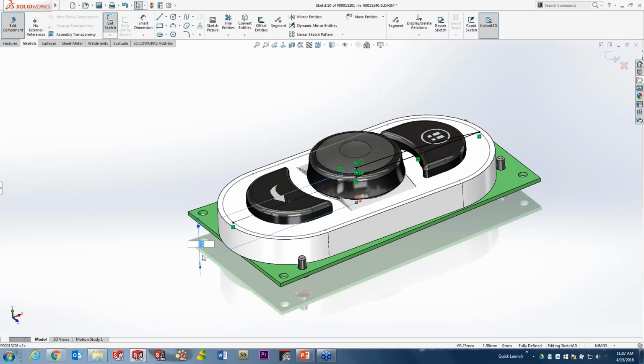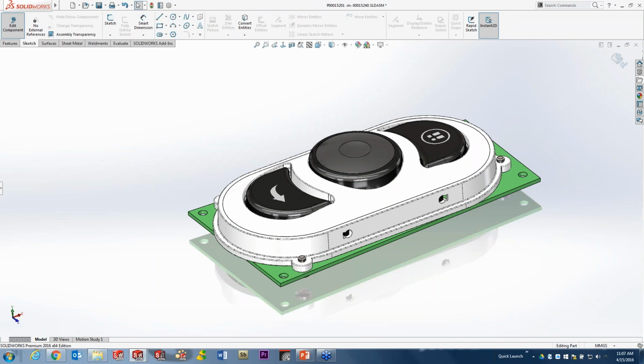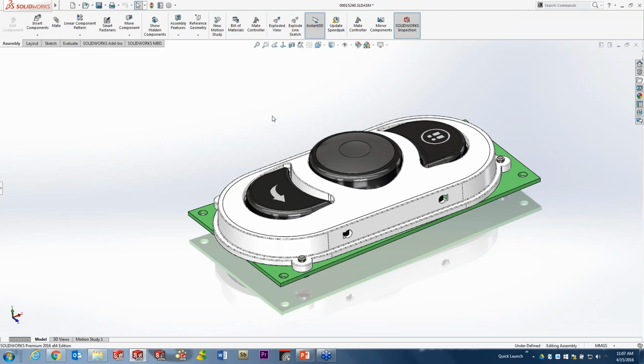Now by making a change to this feature here, we'll just bump that up to 20. Now I have to exit my sketch, which in the upper right-hand corner, we have our confirmation corner. Well, the D key will also bring that directly to cursor position. Now you can again set that to anything you'd like, including a button on the side of your 3D mouse if you'd prefer. But essentially that's going to work on anything in those tool areas. Now I'm editing a part within the assembly which I need to exit. The D key will also bring that confirmation corner over to cursor position. So it is really very convenient, gives you great access to a lot of details, and you'll see that throughout all three parts of this presentation, but quite a bit today.